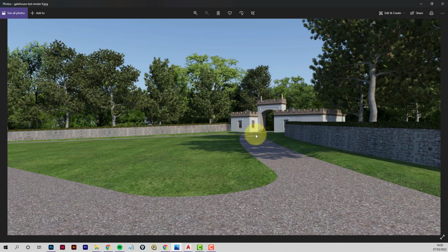How you actually establish the height of the ground in these places. So you do need to be quite methodical. Otherwise you could find that you're redoing stuff. Once you actually look at it, when you get as far as visualization, it's a bit late. You really need to make sure everything's good before you get to 3D Studio or Twinmotion or whatever you're using.